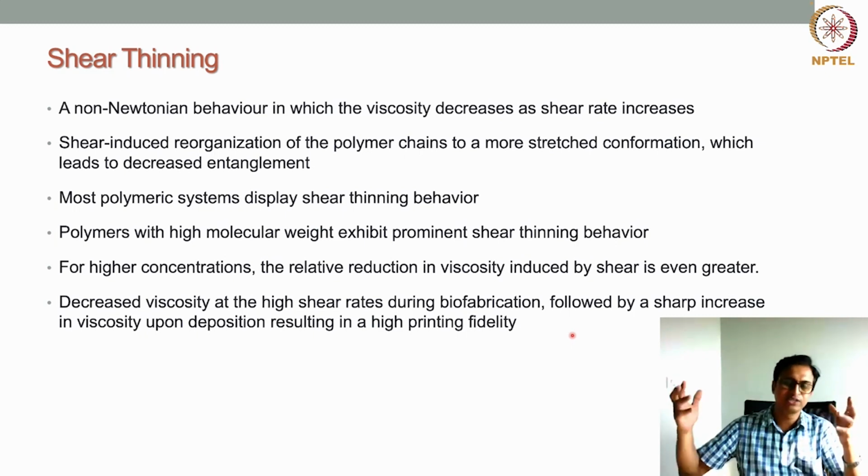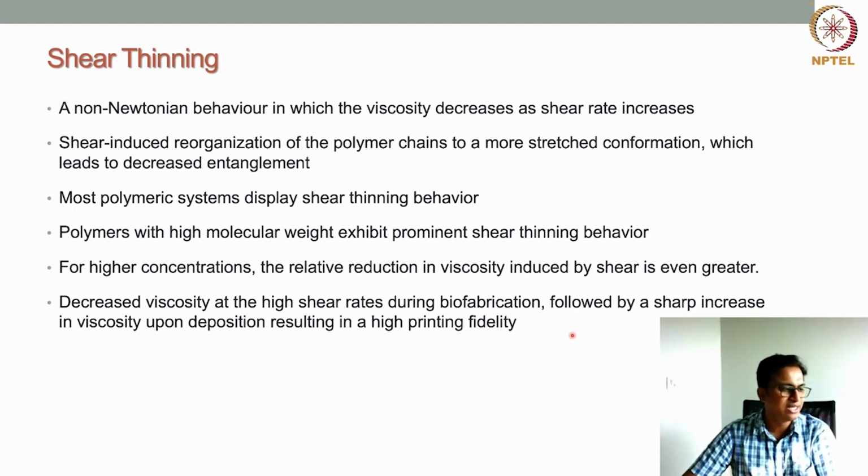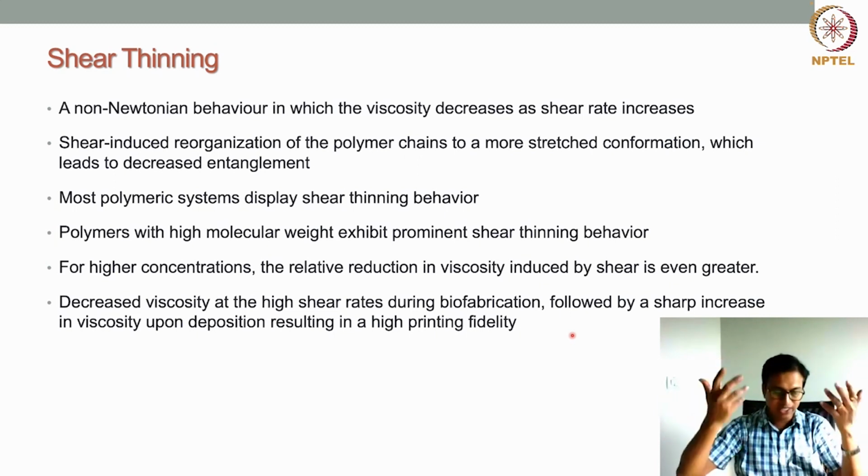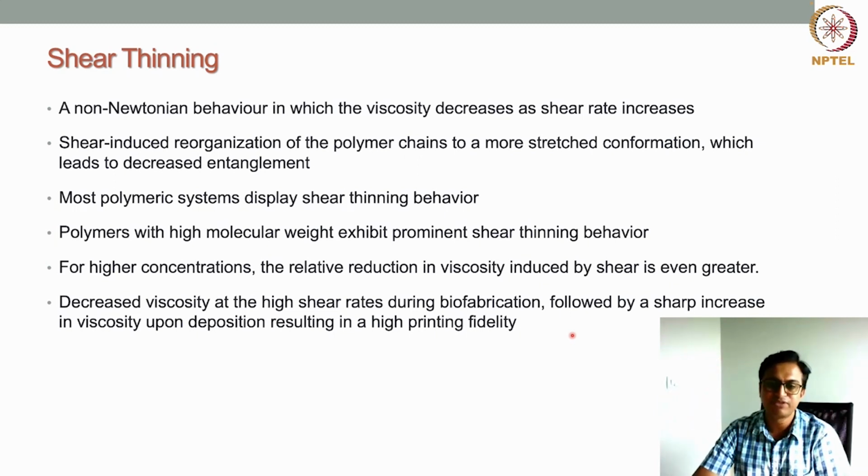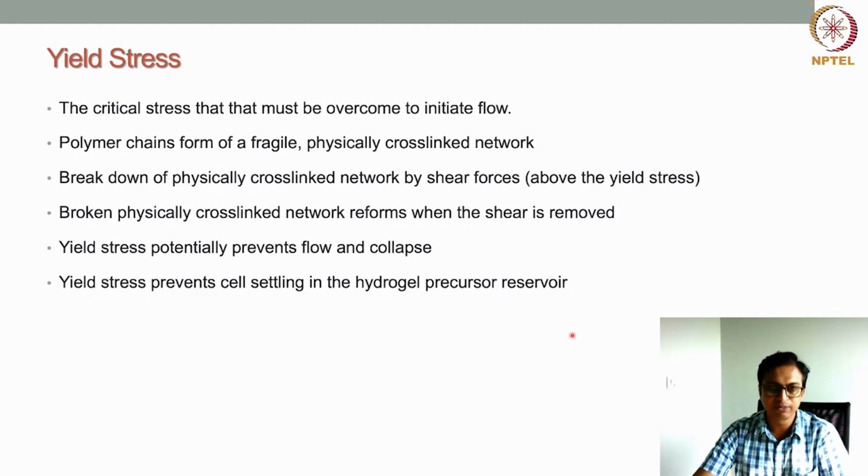Again, when they are outside the nozzle, there is no shear force applied on them, so the viscosity will increase again. So it helps in the printing fidelity. The printing fidelity could be much higher in the case of this shear thinning material.